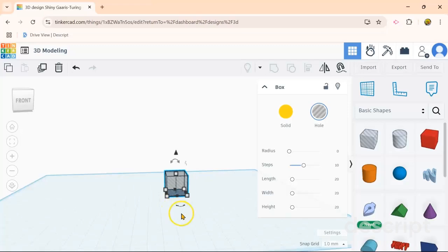We're going to use our square as a solid, and we're going to put a different shaped hole in it. And if you try to send this to your printer just like it is right now, it's not going to do anything because it reads this area as a hole, and you can't print a hole if there's not a solid to hold it. We're going to go back to solids.